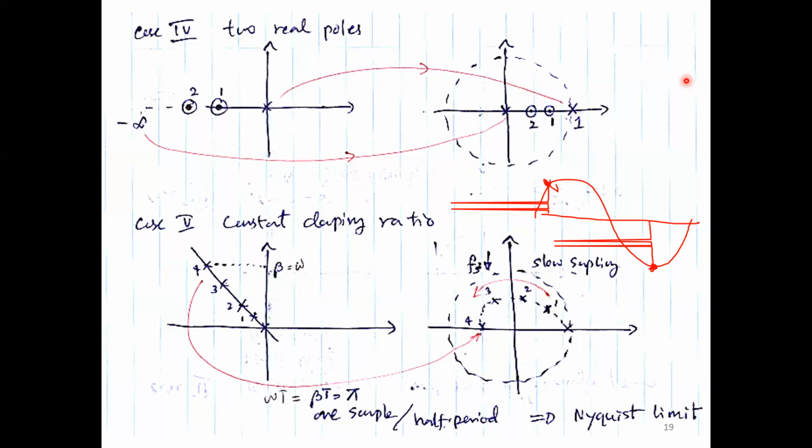But there's a limit, Nyquist limit, and you can't go below that. You can't even operate at Nyquist frequency. That is also not good. So you need to maintain your sampling at least about 4 or 5 times the signal frequency.